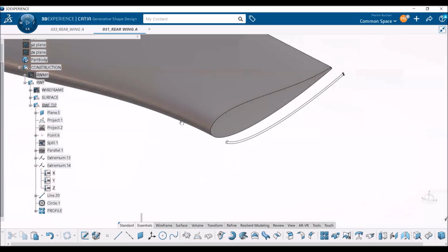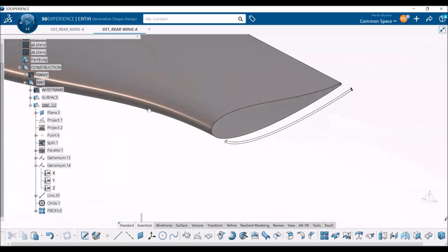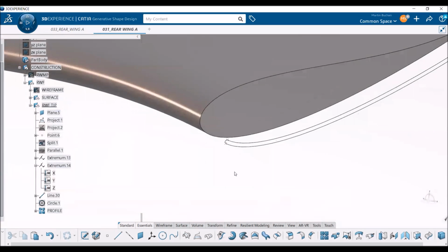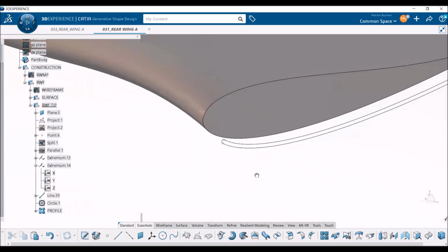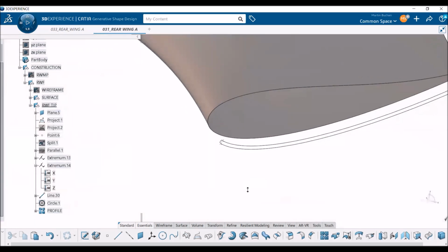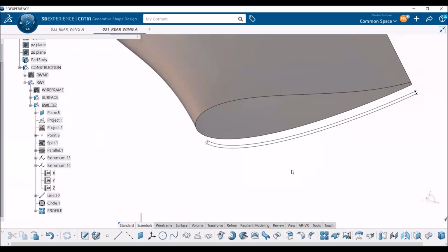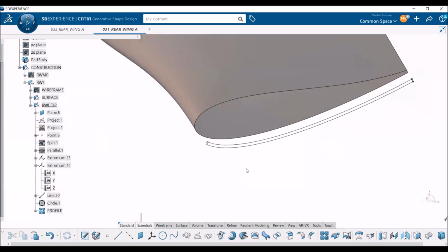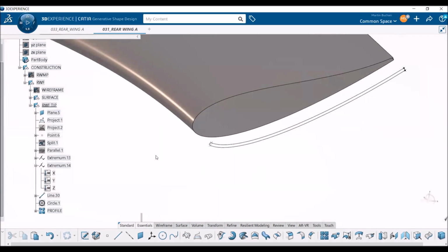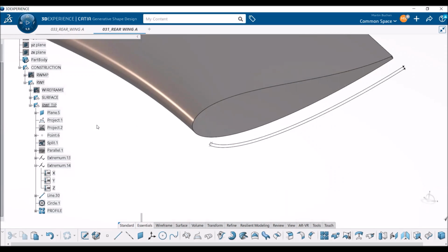And now we need to somehow transition from that profile, from this pretty fat wing profile, into the other profile. So how can we do that now? We have 2 points at the leading edge. We have 2 points at the trailing edge. The trailing edge has the same thickness, so that's easy, but important is the leading edge. Actually, the suction side, so the lower side of that profile is also the same. So the upper side, the pressure side, will have a pretty extreme transition.